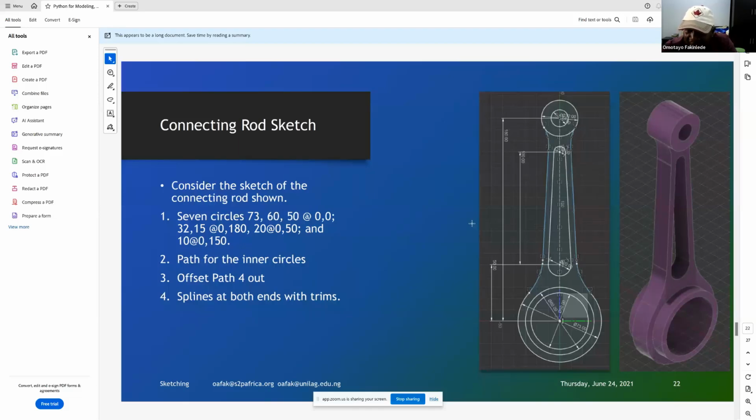And then you will see how to place your dimensions. Both linear dimensions and angular dimensions can be done. And you also check how to do constraining. For instance, you can decide that you have these 3 circles and you can constrain them so that the centers are on a vertical line. So that you don't have to manually find your own way of putting them on the vertical. Tell the thing to put them on a vertical line, and then they will be made vertical to each other.